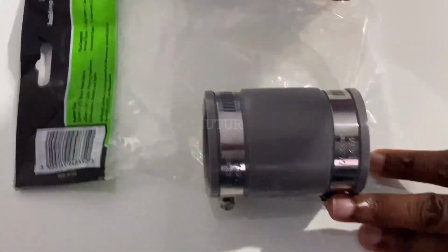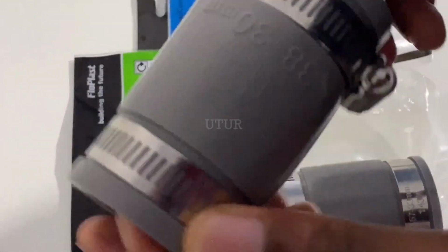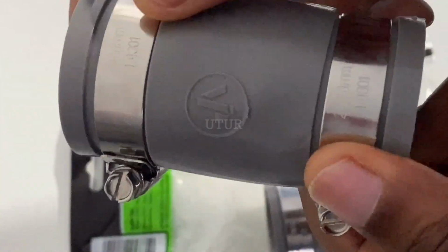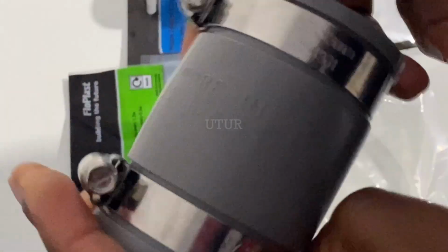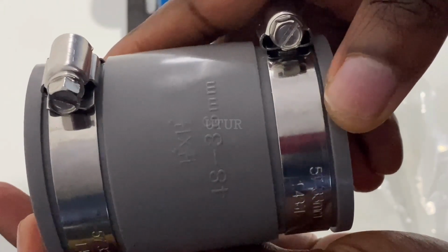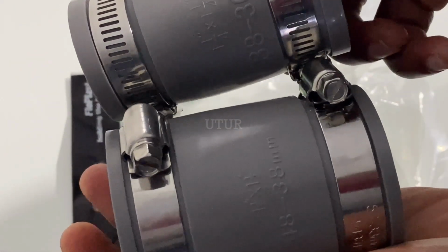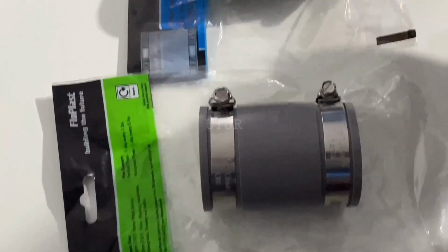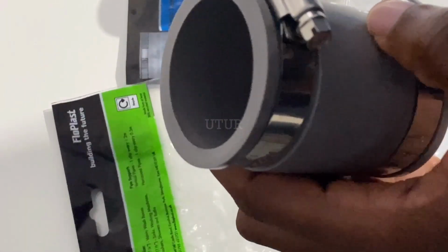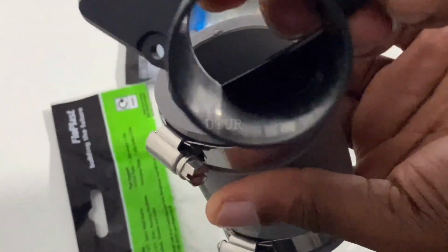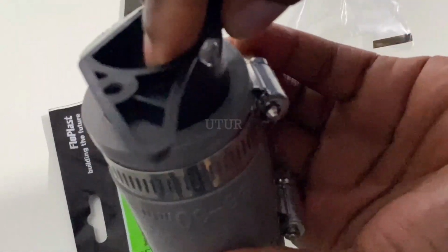So here we've got the W08 40mm coupling, and here we've got the W07 32mm coupling with a tolerance of anywhere between 30 to 38mm, and you would usually find this on 1/4 inch vanity wash basins. The 40mm coupling has a tolerance level of anywhere between 38 to 48mm. And this 40mm or 1.5 inch coupling is usually found in sinks, washing machines, dishwashers, showers and baths. Okay. And since both couplings are versatile, we can adapt them to the vacuum adapter for the circular saw.